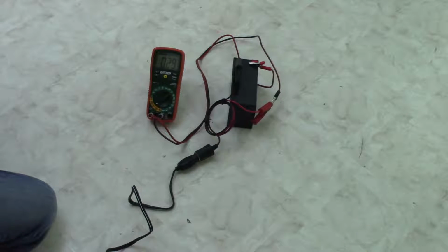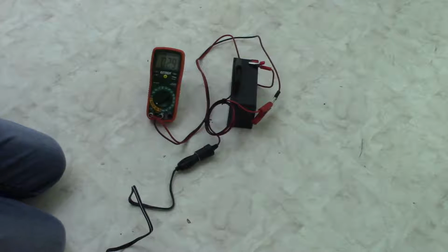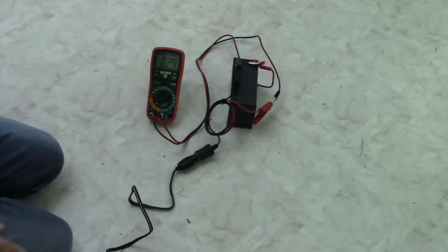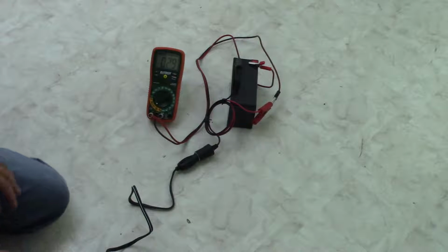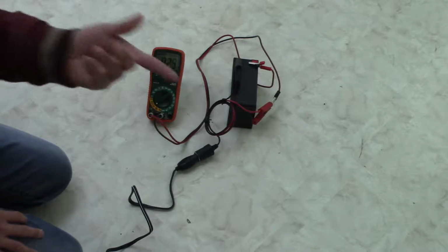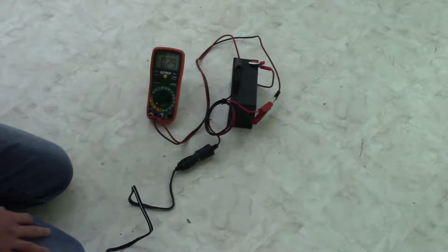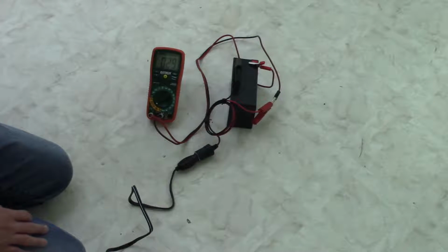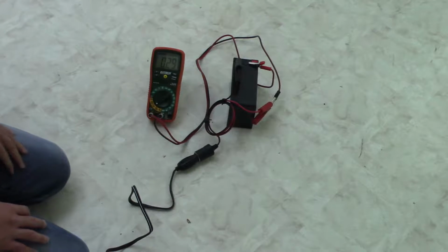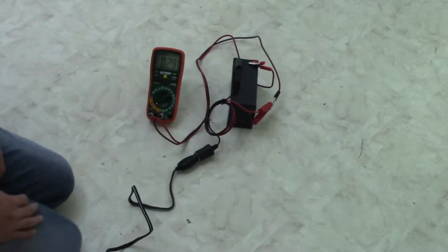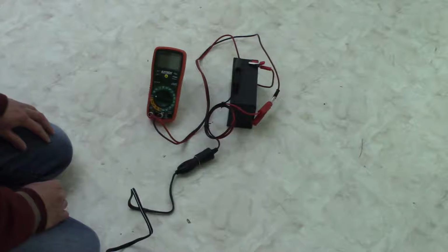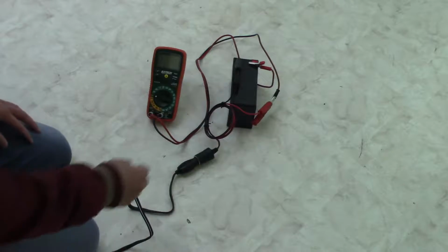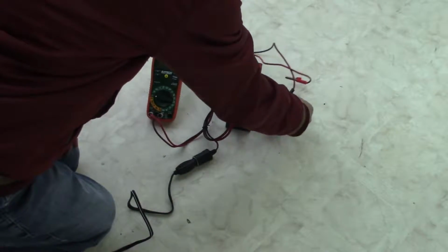So the difference between just under 4 versus just over 9, it's going to be something over 5 watts that this camcorder is using as a result. And of course, when the camcorder is running, it's drawing more current, and so there's additional wattage loss in the battery because of the increased current through that internal resistance. Okay, so yeah, that is pretty much all I wanted to say about that. Of course, we want to disconnect that like so.